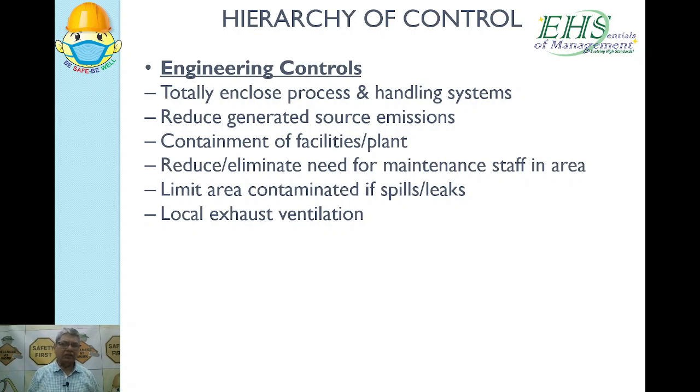Even there are acoustics used in the panels of that generator enclosures. So enclosed. So apart from generators, there are many machines on the shop floors. They create noise beyond the limits, and so you have to create the enclosures for such machines. You have to create enclosure for sandblasting machine, so that the pellets are not going out, so they are stopped. So this is one type of engineering control.